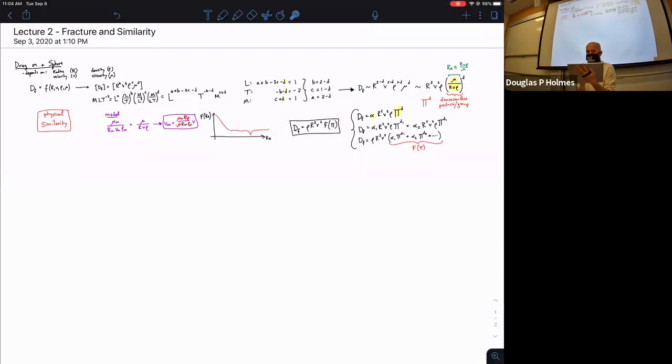What I mean by that is these terms here might be different if you kept D unknown, or B or C or A unknown, you would get a slightly different form. But the end result would be that if you took the drag force and divided it by these dimensional terms over here, you would have a dimensionless number on the left-hand side, and then you would have some function on the right-hand side, f of pi, which we don't know. And f of pi is something that you can measure experimentally.